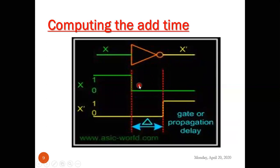When the inputs to both the gates are given simultaneously, both of them will produce the output in the same delay. Say suppose I have one more NOT gate here, I give the input Y where I get Y bar. So what is the gate delay? It is one gate delay only because the inputs are applied simultaneously.